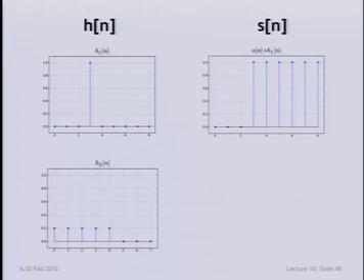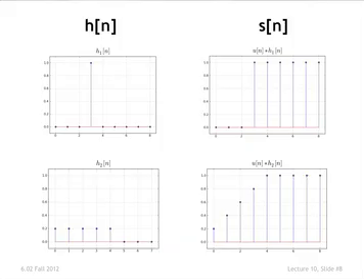Okay, so the question then is, what is the step response? If you imagine that what you're doing to find the step response at any time is summing this from minus infinity up to that time, you will see that the step response is a linear rise like that, and then it settles out. Okay, so you can get one or the other.